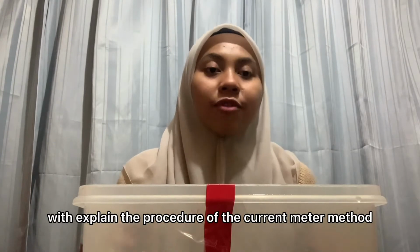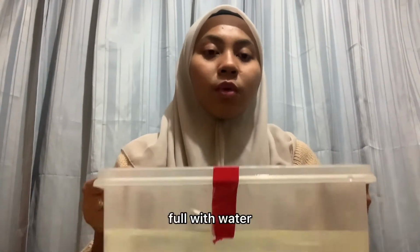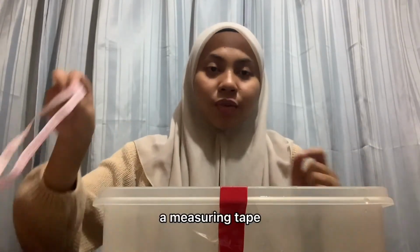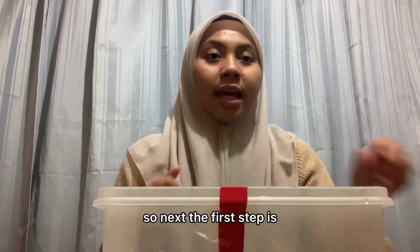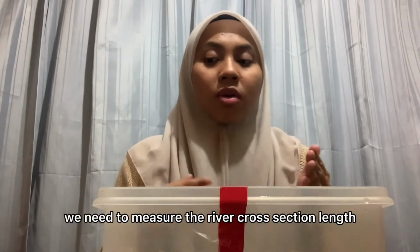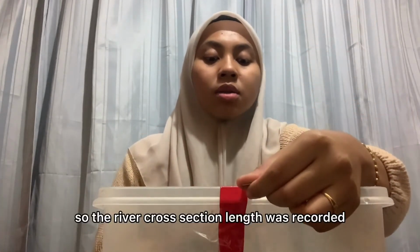Now I, Nabila, will explain the procedure of the current meter method. The apparatus that we need in this experiment are a container filled with water, a measuring tape, a measuring rod, and a current meter. The first step is to measure the river cross-section length using the measuring tape. The river cross-section length is recorded.